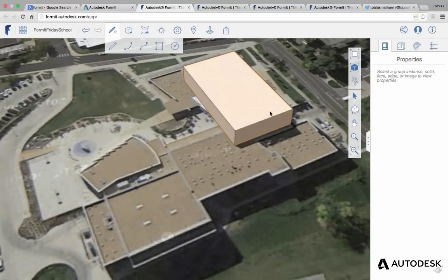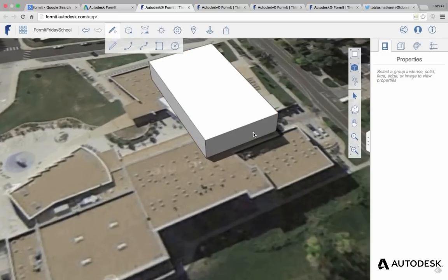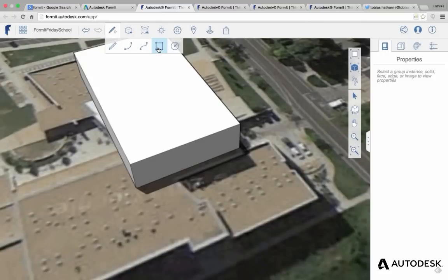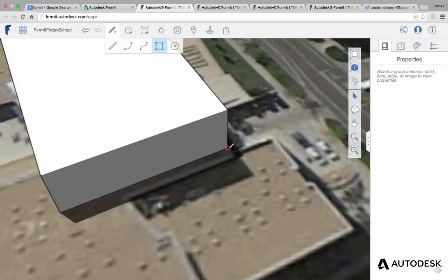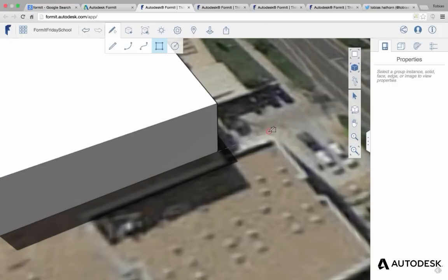And I'll go in the rectangle tool next, and as I hover here, you can see R is the keyboard shortcut for rectangle tool. Go ahead and click that, and here's another snapping inferencing trick. When I hover over this edge, or this vertex, this corner, and then start to come off of it, you can see this red dotted line appear. And that'll help me with the first corner of my rectangle so that it's in alignment with that vertex. So I'll go ahead and click there.